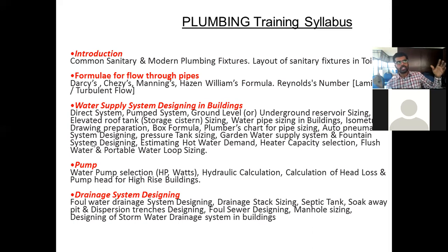So first we dealt with the water from the well and the underground tank. We pump it with the help of a pump to the overhead tank. From the overhead tank, by the help of a water supply connection, it has to reach the individual sanitary fixtures. We have to keep in mind that we need a proper pressure, and if we cannot get it, we can use a stand. If that is not allowed, we can use a pressure pump or a booster pump.